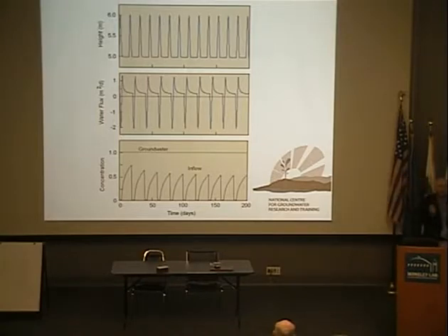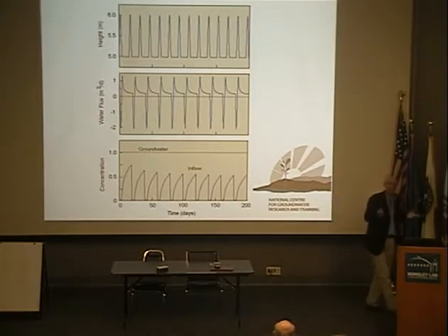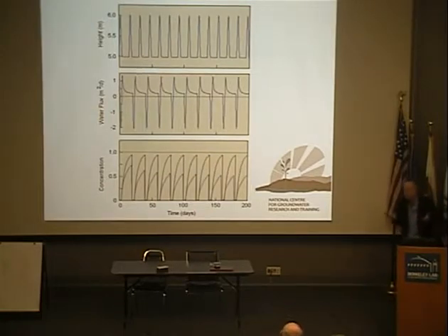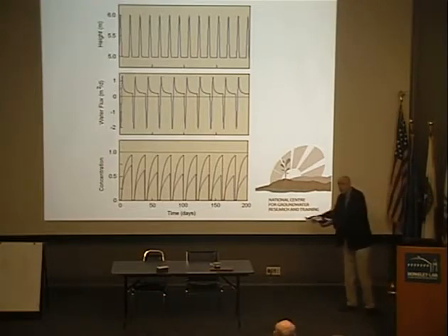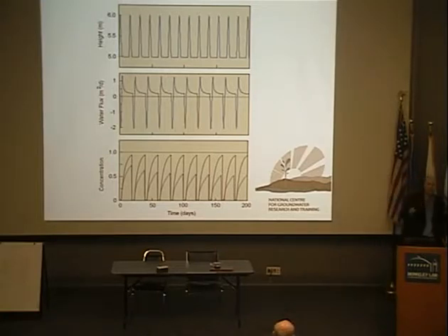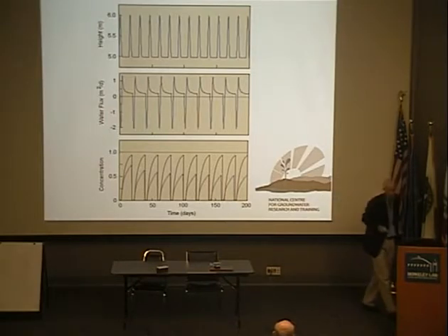So when we're doing these end-member calculations, measuring the groundwater to tell us the concentration discharging to the river could be very dangerous. We will overestimate the concentration. Not as bad with radon. So the red curve now is if you do these same calculations for radon, because when bank storage goes into the stream, it picks up the radon. The radon is regenerated. It doesn't continue to bear that surface water signal. So it's not as bad, but we still need to be aware of it, and with all of these chemical separation methods, the stability of the end member is something that we haven't probably focused on enough.